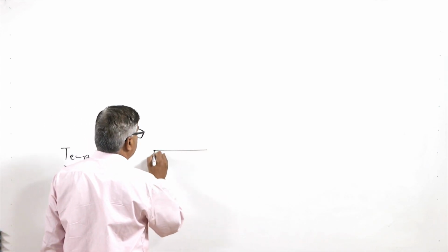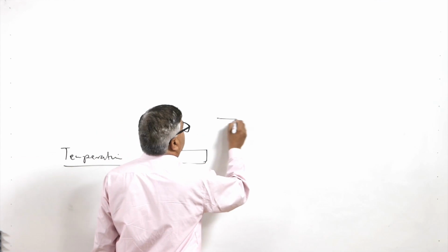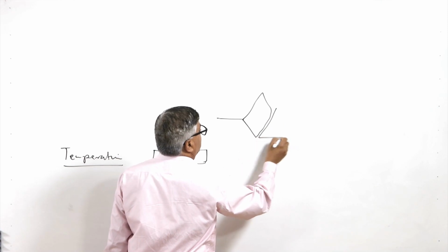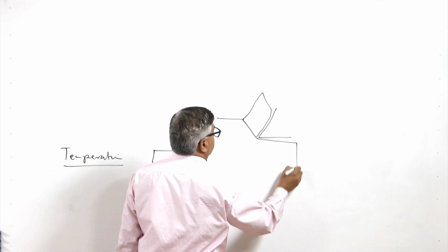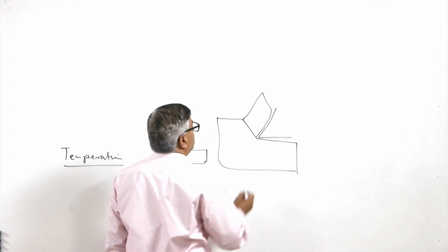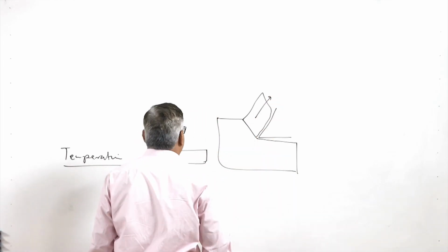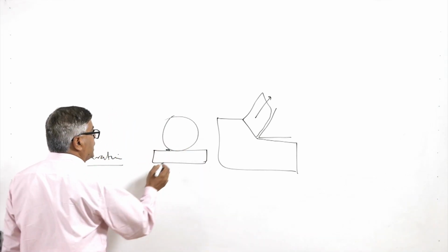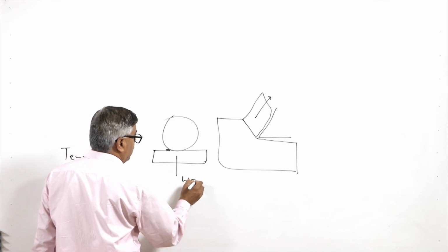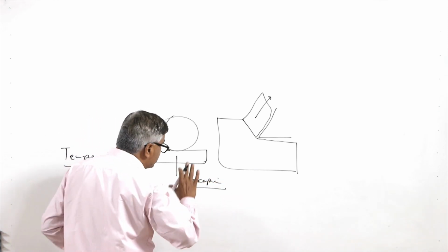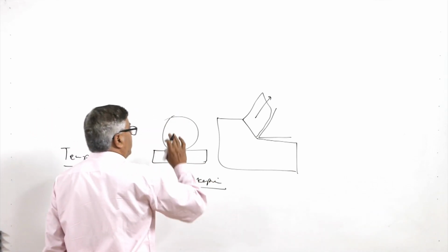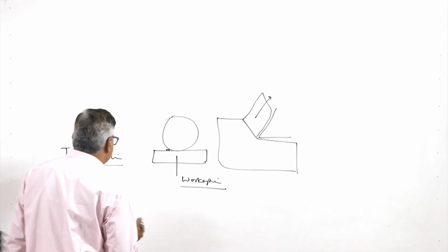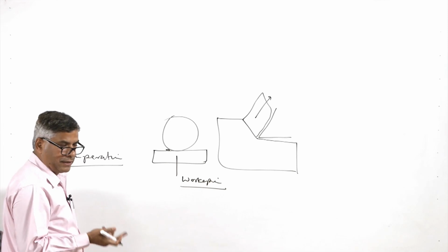If we compare the scenario with conventional machining, in conventional machining the chips carry away a lot of the heat generated in the primary shear deformation zone and the secondary shear deformation zone. So the chips carry most of the heat, while in the case of grinding, the chip size is very small and they are very fragmented. So the heat generated is mostly carried by the workpiece. Since most of the heat is retained by the workpiece, and part of it is also retained by the wheel, the workpiece is very badly affected by the heat generated during grinding.